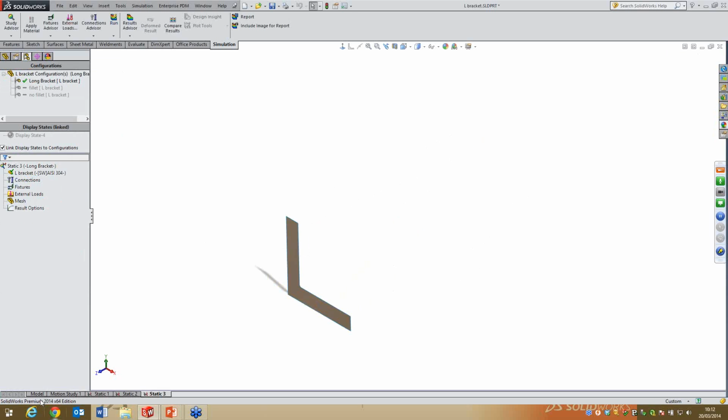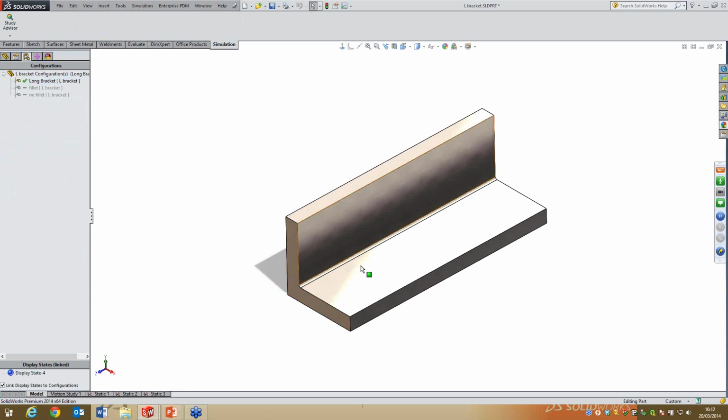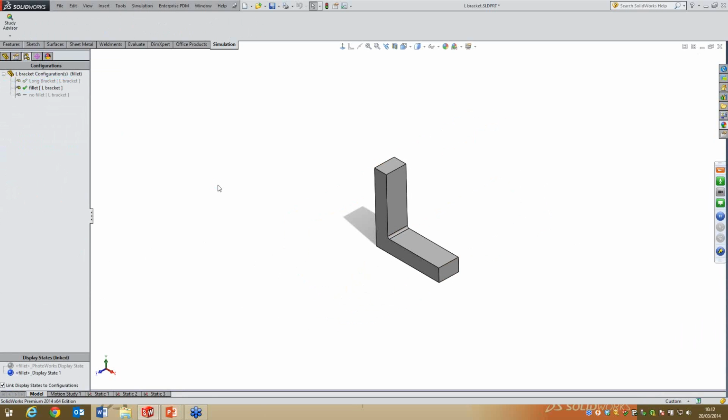So just remember, if it's really long like this, and you're doing a section through it like that, use the strain type of measurement, so the plane strain. If you're using a very slender model like this, then use the plane stress approach.